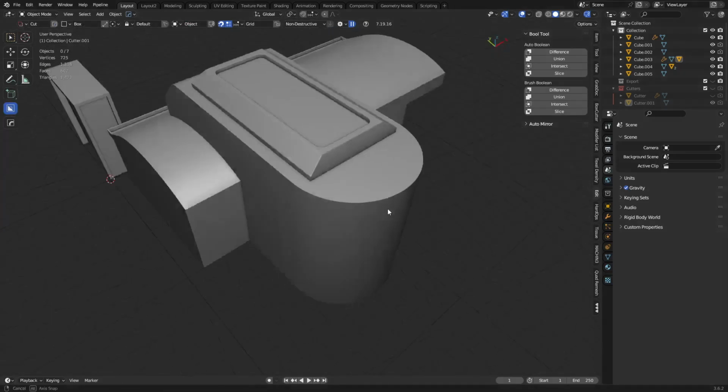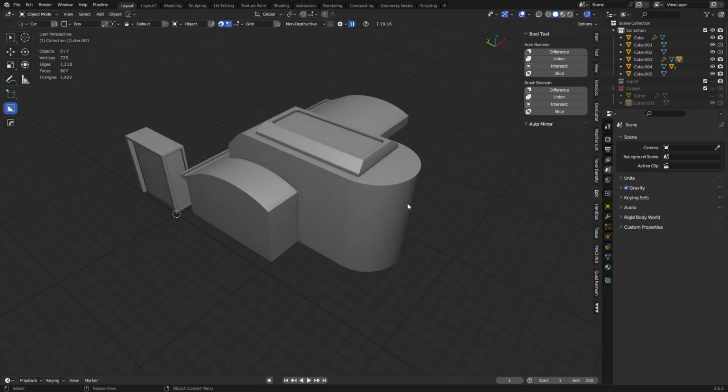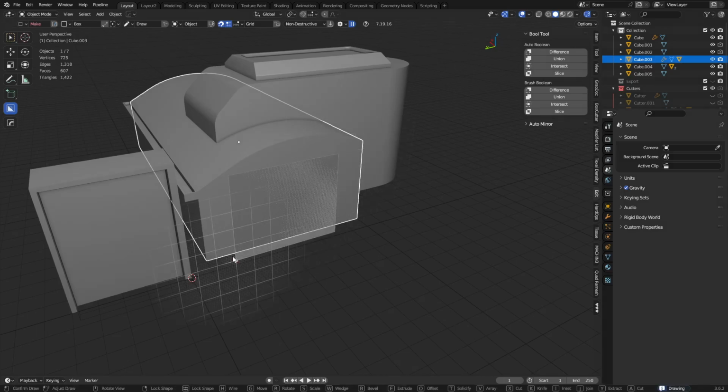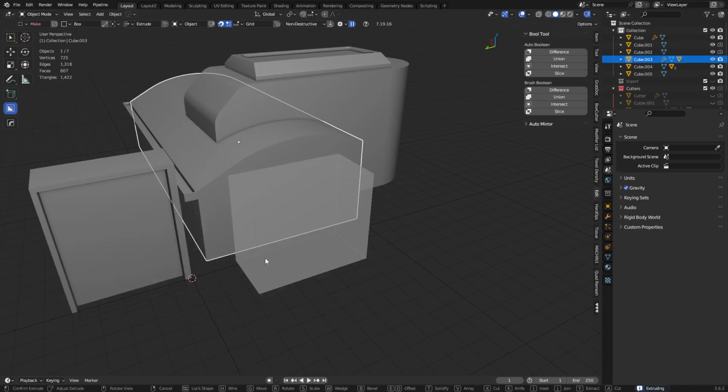And at some point, when you do turn this into a building that you're going to use in a game or whatever the case, there's two different methods you can approach doing buildings. You can try doing center aligned walls, like I taught in most of my modular series videos, but you can also just do a whole building within a footprint and then have the walls on the interior side cut inwards as well. And so when you want to do extensions to a building, you can certainly do that just by doing a new extension. So you might just cut something here, for example. You can see that origin point's not lined up quite right.